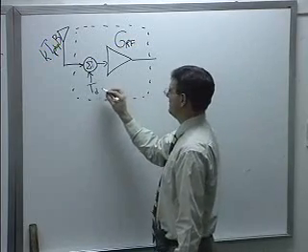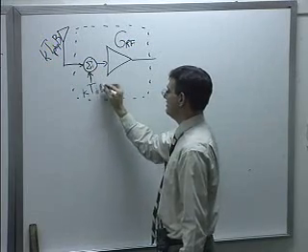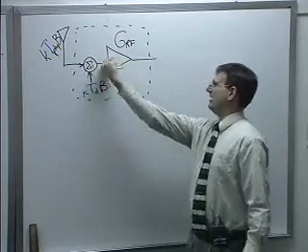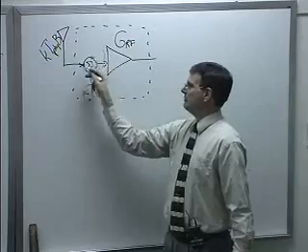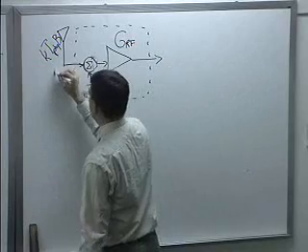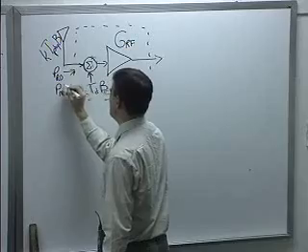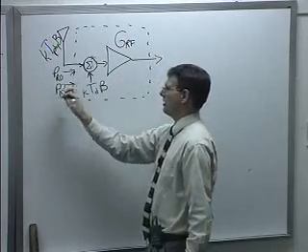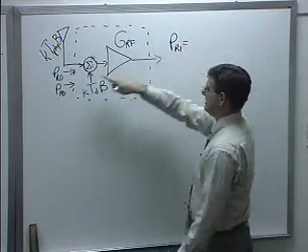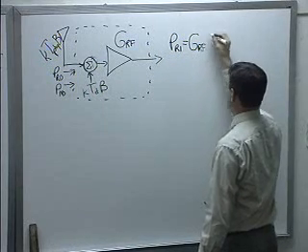So think of this as noise power, k T_D times the bandwidth of my signal, is going to be added into the signal at this point. And we typically define it to be before the block of gain. So what comes out of here, if this is P_R0 going in, P_N0 going in as well, receive power and noise power, what comes out is basically my P_R0, my desired signal power, times a certain amount of RF gain.